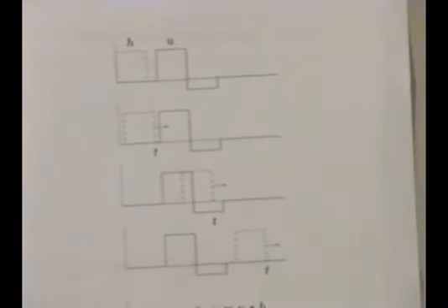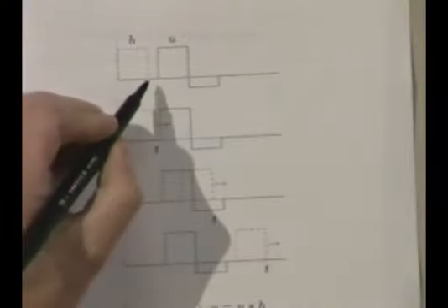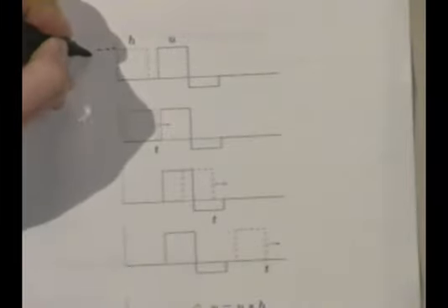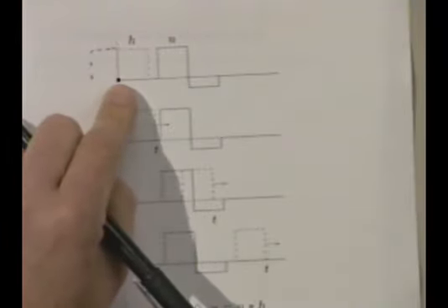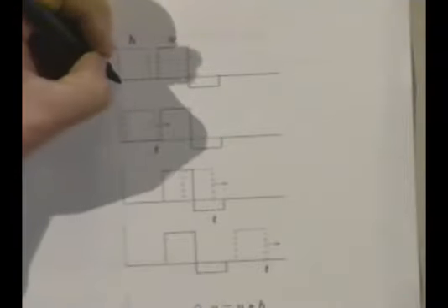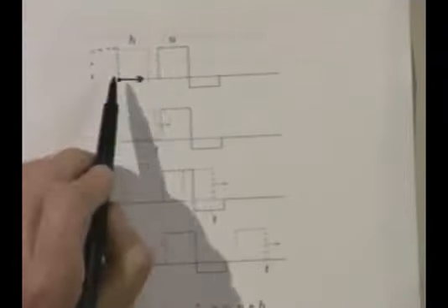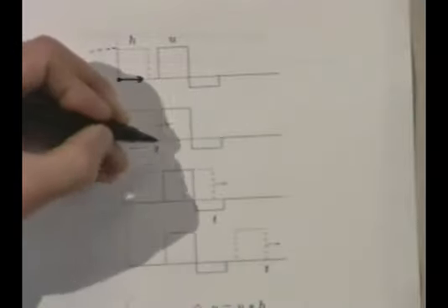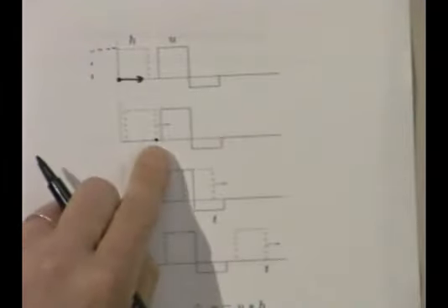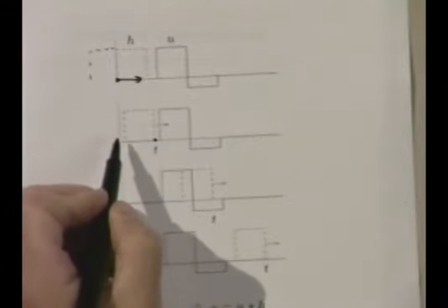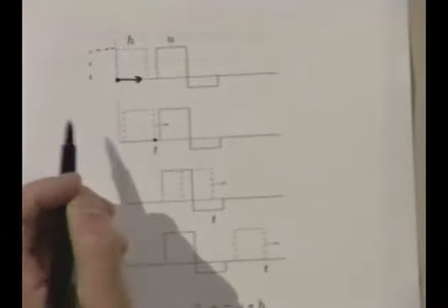Well, the first thing to do is to flip h backwards, so it looks like that. So you flip it around, looks like that. Now you imagine you grab one part of h, the part that's at 0, and you drag this along. At this point I've dragged it to time t here. So what I have is a picture of h, but going backwards in time and shifted.